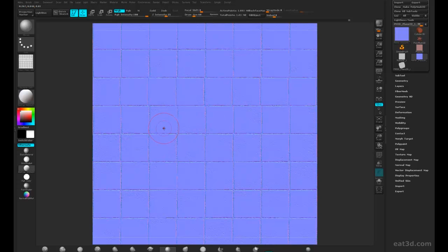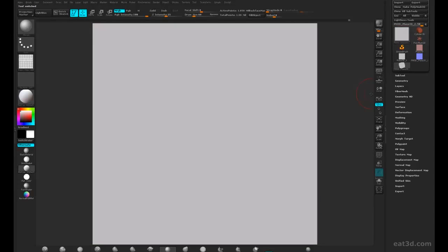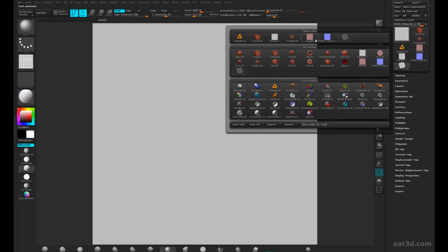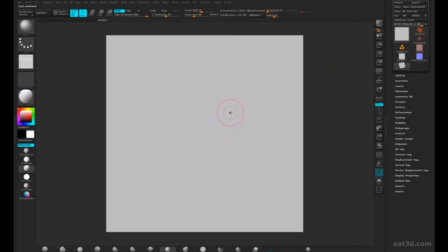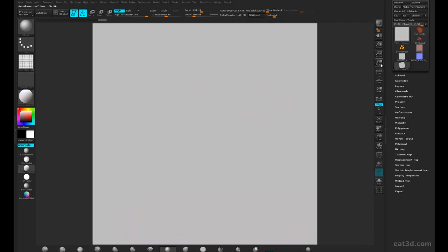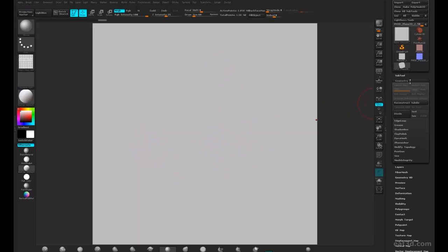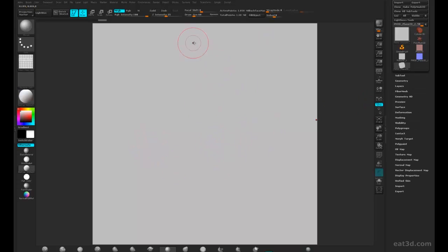So all that I've done is I've gone in and I've created a plane 3D. Just go in here, create plane 3D. So I've created that. I've zoomed out, pressed F on the keyboard to make sure it's framed, so I know that then it will tile. And then I've gone back to anti-alias in half, so you get some nice quality there. I've gone into geometry, and as you can see at the moment we're sitting at 1.5 million total points.